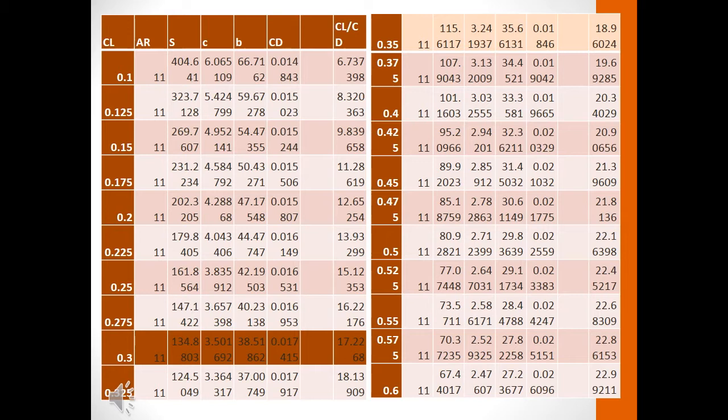As the lift coefficient increases, so does the drag coefficient, so we cannot simply choose an extremely high lift coefficient for our wing. It is also unrealistic to have such a small wing at these high lift coefficient values.